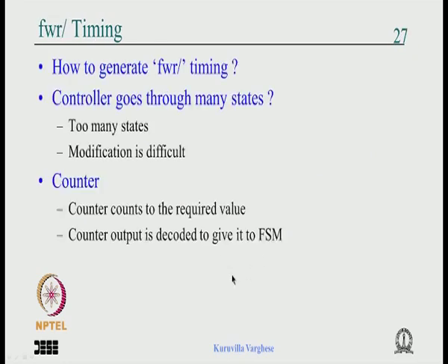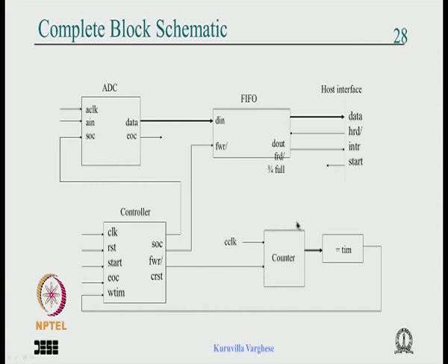So we decided to put a counter as a subsystem, the reset of which is controlled by the same controller or state machine, and when it is decoded for a particular value, it gives a time. So the idea is that when the FIFO write is given, the reset is removed and it starts counting, and you wait for this time.